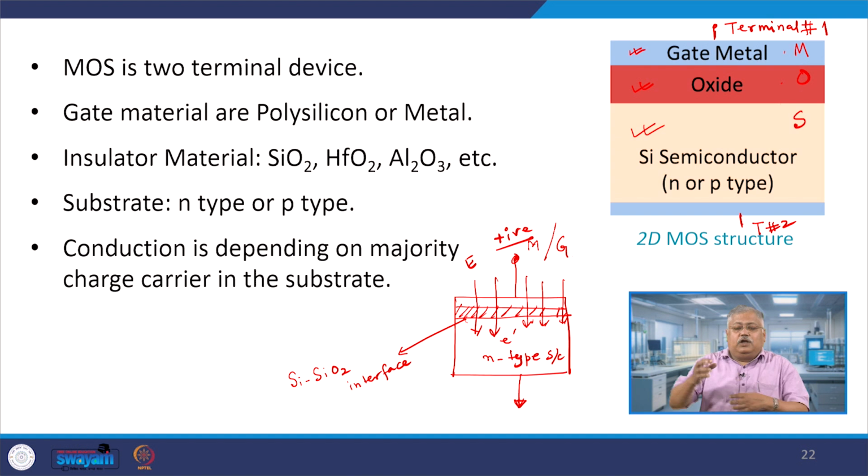When you give a negative bias, all the electrons will be pushed backwards, and whatever small number of holes are there will be attracted. But please understand, when you have an N type semiconductor, electrons will be the majority carriers, but you will also have a very minuscule number of holes available there. They are known as minority current carriers, right.